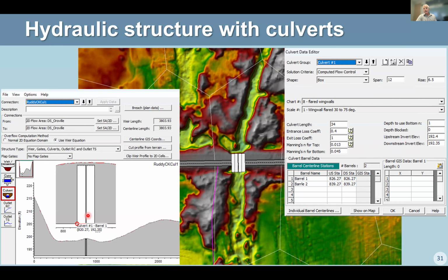If you have a large model, and small culverts that really aren't influencing your inundation, you might not need them, or you can just open them up like I did before. If you have something that you think is significant, you need to include that in the model. So that's the terrain. There are other aspects of that, but I've given you a feeling for how it is manipulated and included.